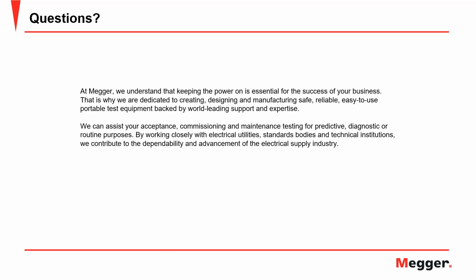In addition to that, trending is a very important factor. When a transformer is being manufactured, typically the factory would provide the baseline values or the reference values, and it is very important to compare your numbers with those reference measurements. So to give a quick answer to this very in-depth question, yes, the values would differ for different kinds of transformer, the insulation used in it, and the way the transformer is being utilized.